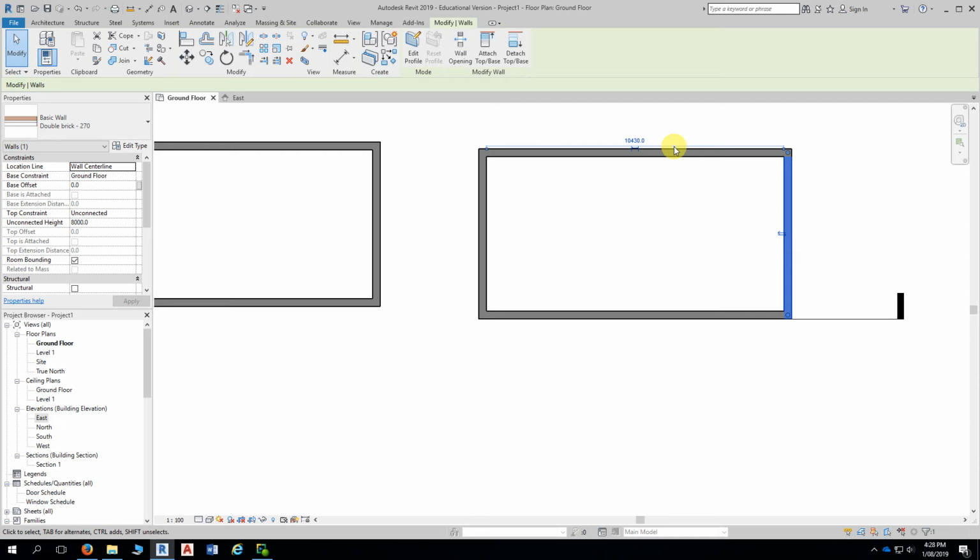So we're just exploring some of the ways we draw, and also some of the drawing aids that Revit gives us to help us draw. And I guess the bottom line here is that if someone gives you an A3 sheet with a floor plan on it and you have to replicate that in Revit, you do not draw your walls exactly to their length initially.